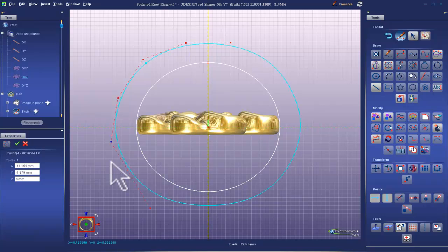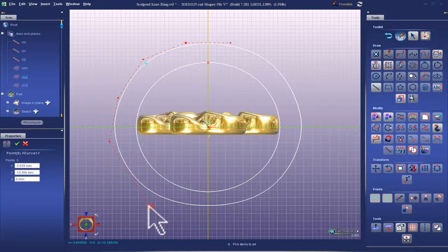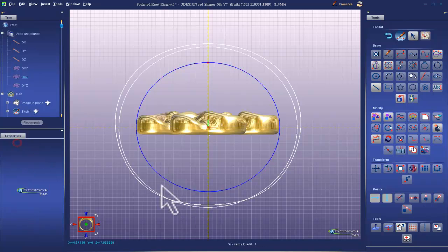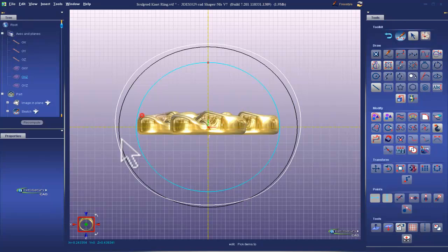This is about 2 millimeters here, so I am constantly measuring. But because I have my grid snaps set up this way, I can just see exactly where I'm at in terms of the dimension. And I want it to be slightly off round. Another trick I sometimes do is I'll do an offset of, let's say I want 2 millimeter thickness. I'll go 2 like that, and then I'll actually freeze it.